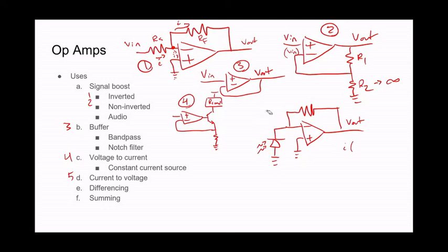The amount of current that flows this way is proportional to the amount of light that strikes the surface. But because of rule number 2, we know that this must be 0 volts. So those electrons have to come from somewhere, ergo they come from up here. This is our feedback resistor RF. So we know that the voltage out, or V out, equals RF times I, or I times RF, is how we normally indicate that. Therefore, the voltage out is also proportional to RF times the amount of light striking the surface.